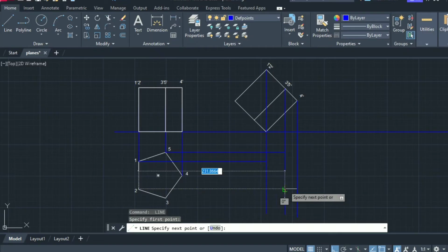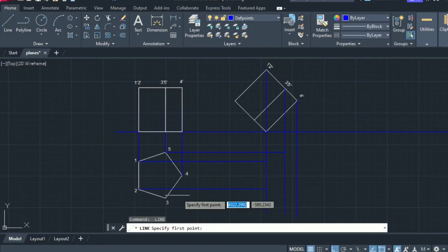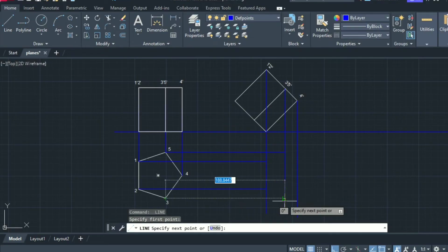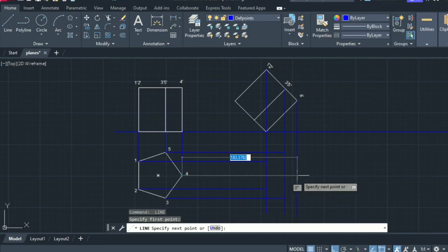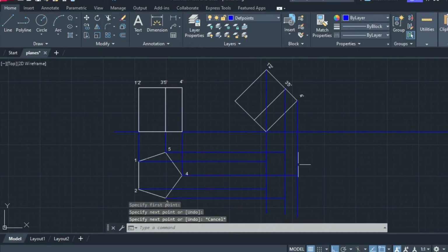Same case from point 2, point 3. Just check where is line 3 dash. And then last, point 4. So once you recognize all these points, you can join these points with a straight line, because when you'll be looking from the top, this whole base is directly visible to the observer.